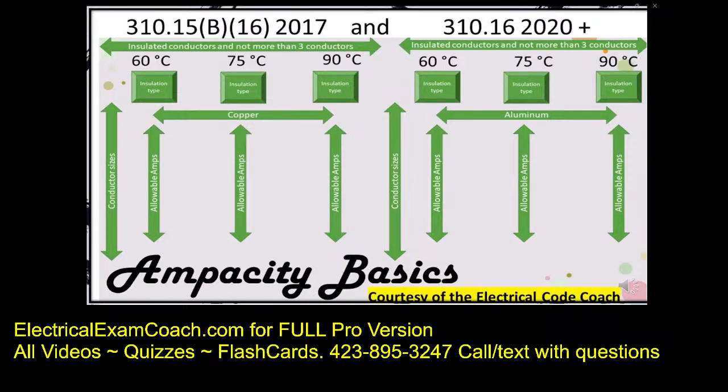The first distinction we want to make with this table is that it's actually two tables. On the left-hand side is going to be for copper conductors, and on the right-hand side is going to be for our aluminum and copper-clad conductors. Left-hand side copper, right-hand side aluminum. And if you'll notice, they mirror each other, but in the NEC, it's smushed all into one table. Now let's take a look at what all this information means.